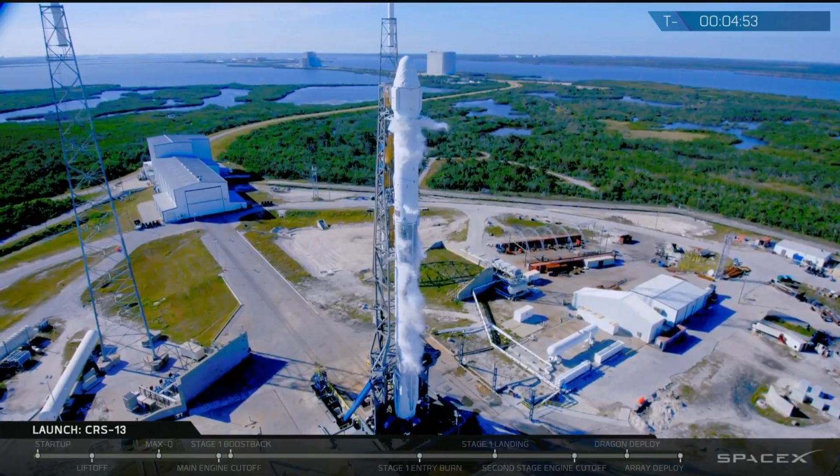Falcon 9 is now performing its final checkouts to make sure that all of its primary systems will work in flight. Those checkouts include the communication systems and the avionics systems, all of which are looking totally nominal, just the way we like it. The engine chill began a few minutes ago at T-minus 7 minutes. That gets the engines cold enough to safely move propellant without causing it to accidentally boil.